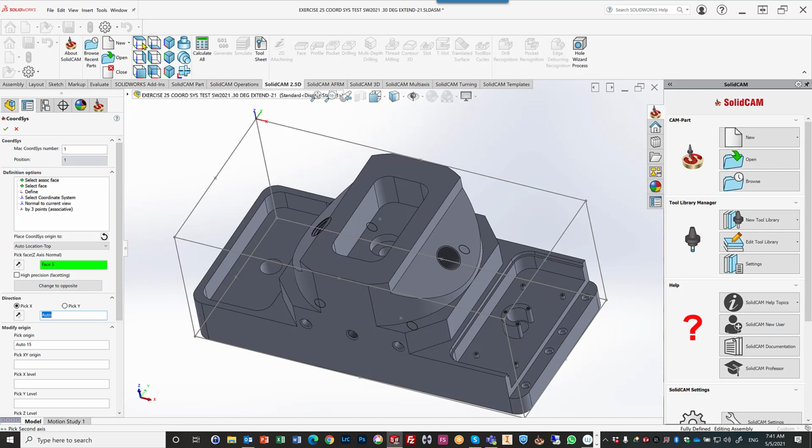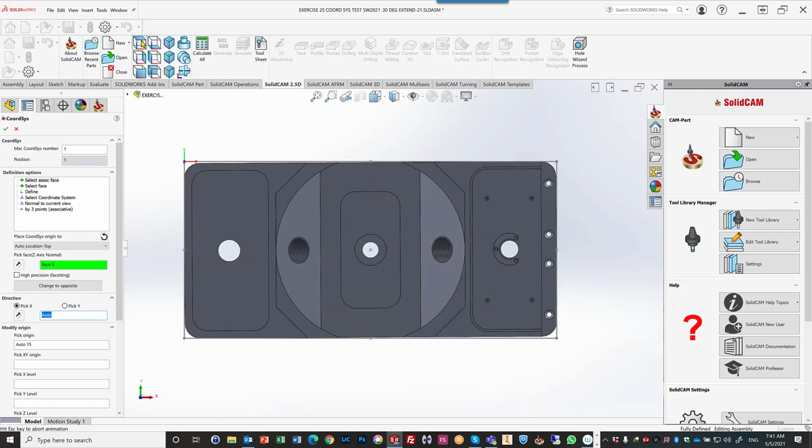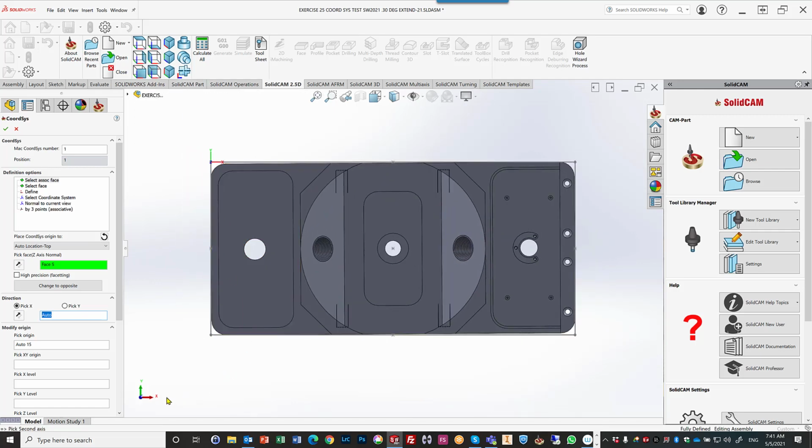If I click the top view, you'll see that this is the plane, but you'll also note in this particular case that it's not really in the corner over here. Why? Because this particular part was drawn at 0.3 degrees on an angle, let's say in CAD, for example. So this was always problematic.